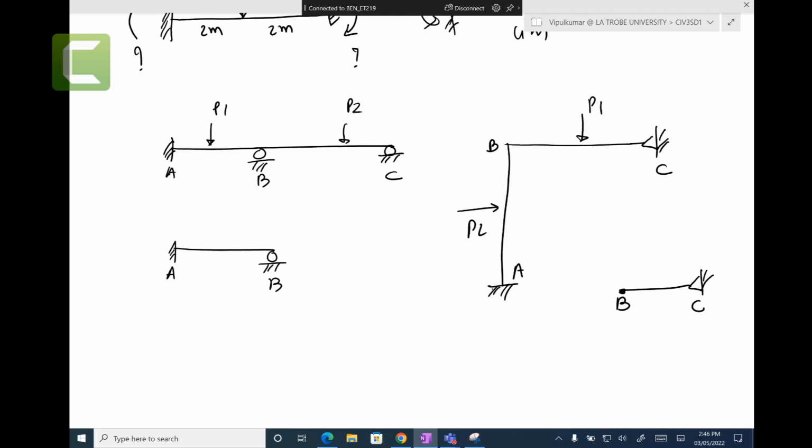Look, here note axial deformation. This guy P2 is going to push this point B, so you have axial deformations in here. In the sense that beam elements have vertical forces and moments. But in here, you have vertical, you have moments, and you have this one. That's the difference. In frames, you have these axial forces.